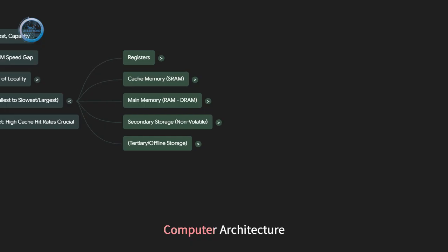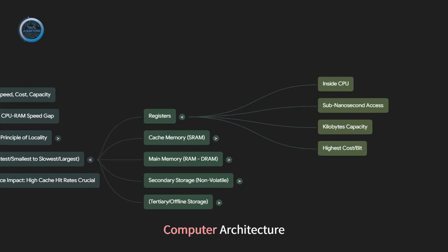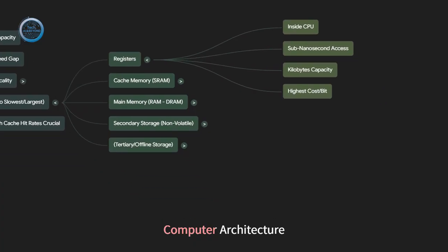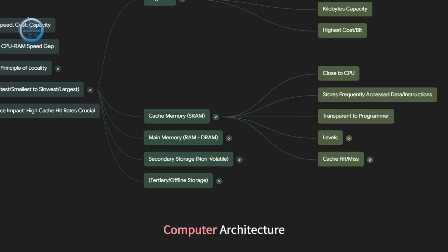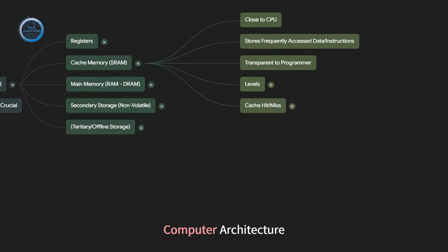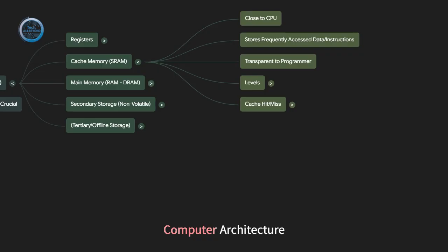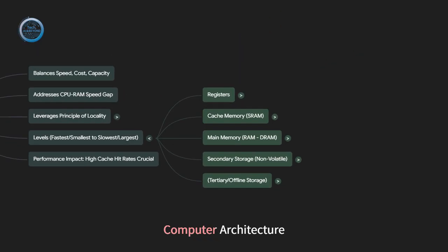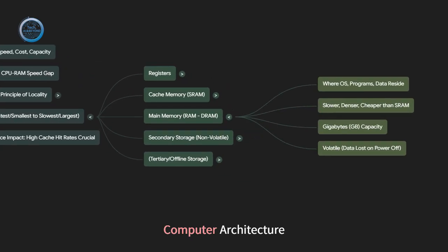It specifies the actual instructions, the opcodes for things like arithmetic, moving data, controlling program flow. It defines the registers that software can use, the different types of data the CPU can handle, integers, floating point numbers, maybe vectors. It also specifies how memory locations are addressed, the addressing modes, and the mechanisms for input and output. It's the complete programmer-visible interface to the hardware.